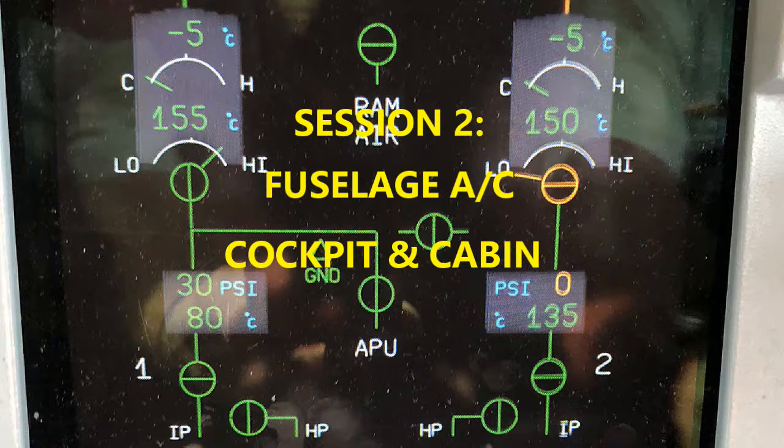Okay, let me repeat that. Here's the difference between the primary heat exchanger and the main heat exchangers. Your main heat exchanger's job is to cool the hot air coming from the compressors of the air cycle machines, because the air cycle machine is actually going to compress the air. By the way, the air cycle machine is located between the condensers and the plenums, but its job is to compress that air and expand it. And the fan plenums are attached to the air cycle machines, and all of this is installed in the ram air system.